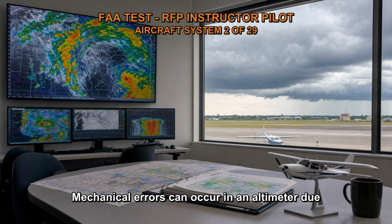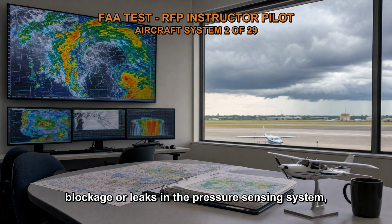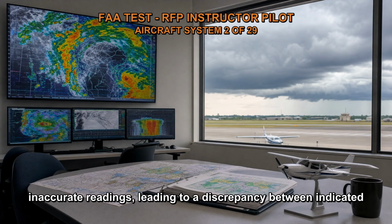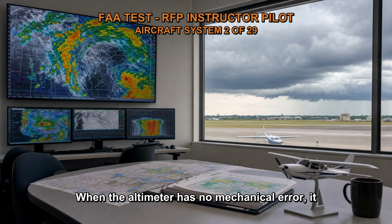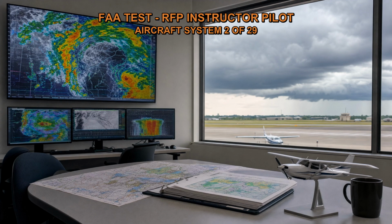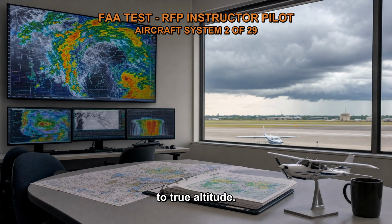Mechanical errors can occur in an altimeter due to various factors, such as instrument calibration issues, blockage or leaks in the pressure sensing system, or improper instrument installation. These errors can cause the altimeter to display inaccurate readings, leading to a discrepancy between indicated altitude and true altitude. When the altimeter has no mechanical error, it means that the instrument is functioning correctly and providing accurate indications based on the atmospheric pressure measurements. In this case, indicated altitude will closely correspond to true altitude.